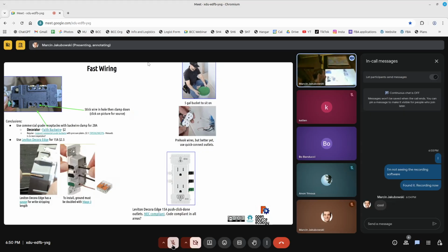We did it up here in the warm, and then it just takes minutes. Where it says the little stripping gauge, you just strip it to that length, and then there won't be any extra copper sticking out. It'll be just right. And they have outlets on the back, so you connect one to the next one using the same method, and it's very neat and fast. So you can gang them multiply to any number you want. Yeah, this is great. So here's the standard route. I mean, with that, you've got to turn those curls and screw down that screw, all of that.